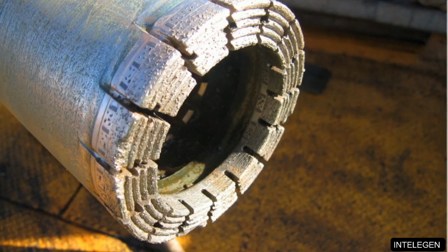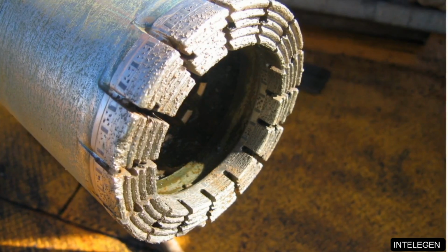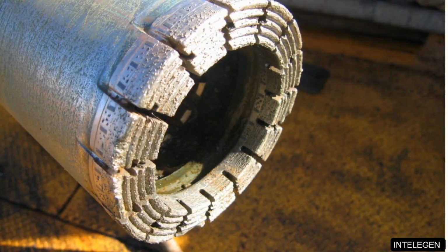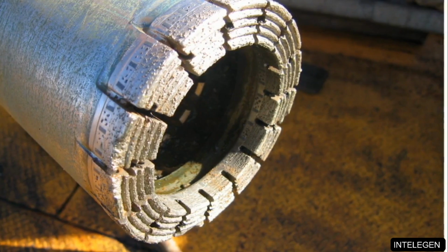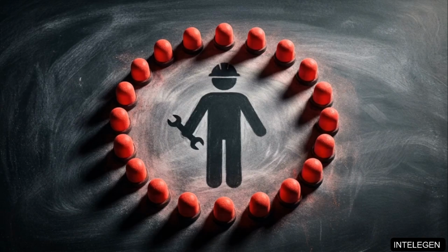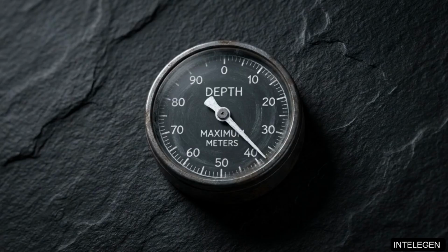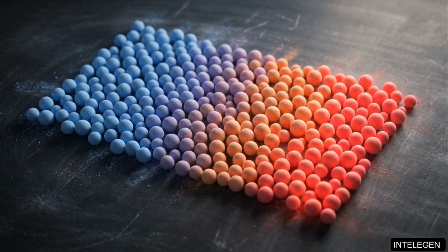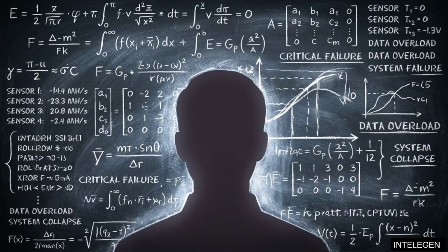To prevent catastrophic degradation, modern components must be fabricated from advanced alloys, including nickel-based superalloys. These are paired with high-temperature drilling muds that act as a hydrostatic counterpressure to the plasticizing rock. But hardware is only half the solution. At 11 kilometers deep, thermodynamic fluid shifts can happen instantly. Human reaction time is too slow to manage the variables required to maintain borehole stability.